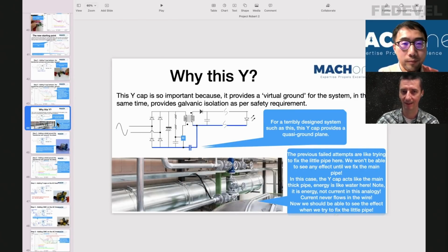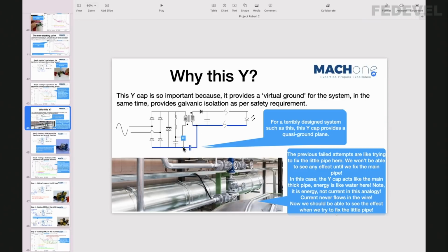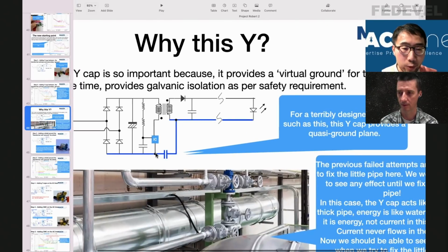What happened? I explained it, but I would like to hear you explain what happened when you placed this capacitor there. To understand it, you need to understand the common mode voltage. In this case, the common mode voltage is between this point, which is your primary side 0 volts point, and this point, which is your low voltage 0 volts. If you measure the voltage difference between these two points, you will see a big voltage jump, and particularly in the radio frequency range, that's causing the problem.